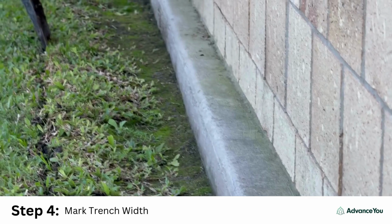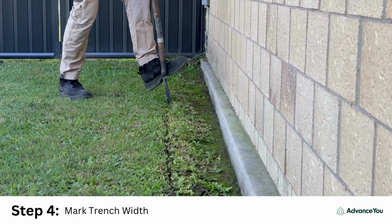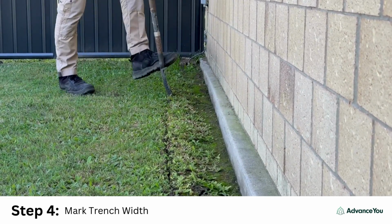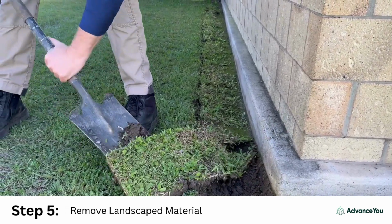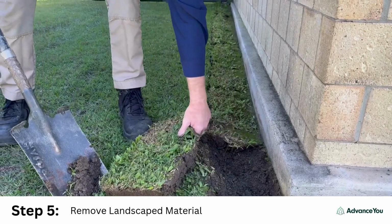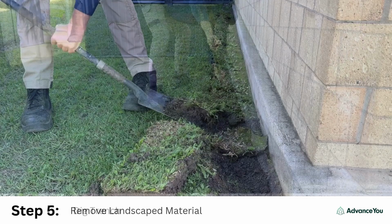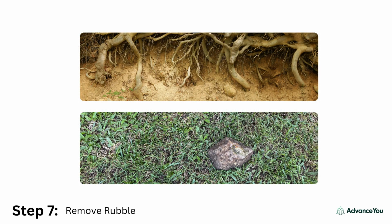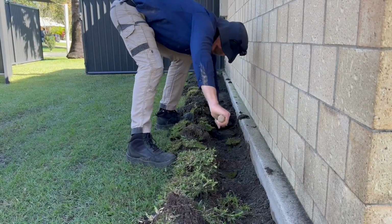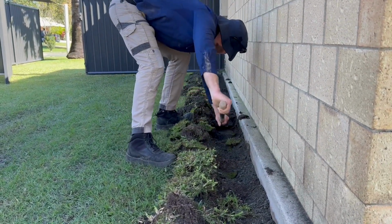Next, Shane marks out the 150mm width of the trench he must dig. When using a shovel, always practice safe manual handling techniques. To ensure you have a happy customer, carefully remove the top layer of grass, placing it next to the trench edge to return later. As you are digging, remove any rubble, such as stones or tree roots, to ensure the termiticide can bind to the soil well. Termites only need a gap of 1 to 2mm to bypass the treated zone and enter a building.